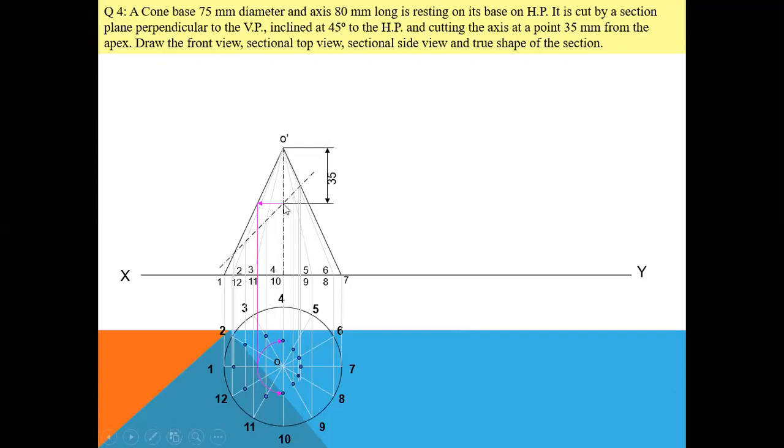The trick is, as Abhishek sir has discussed, from this point, draw a horizontal line till this end. Then from this point, drop a vertical projection line on this O1 length. Then take your compass, measure this length to this length. Keep your compass at this point and complete a semicircle. You will get one point for O4 and the second point for O10.